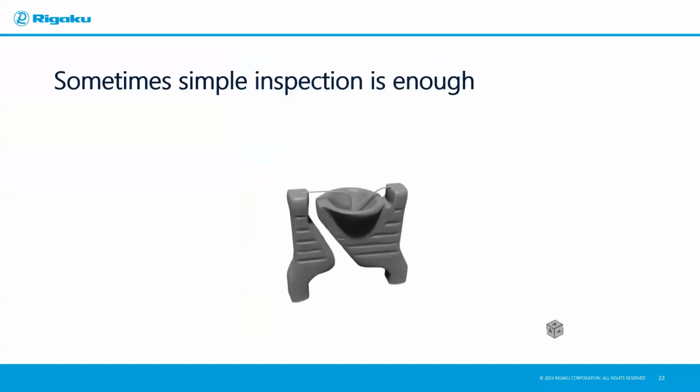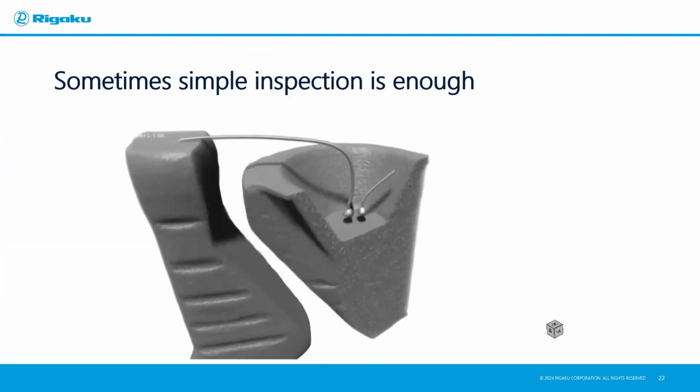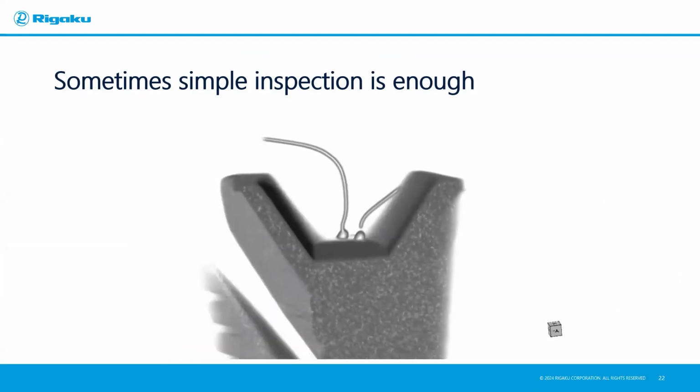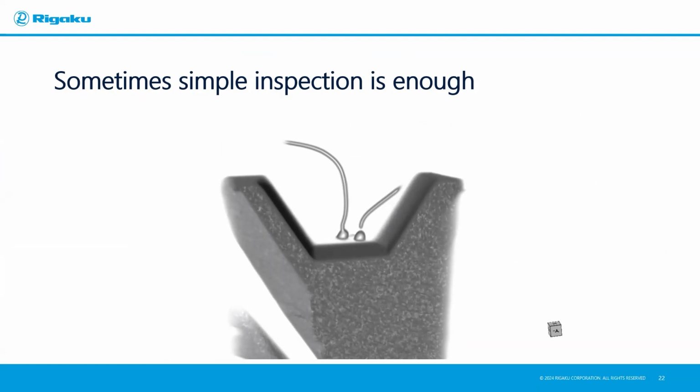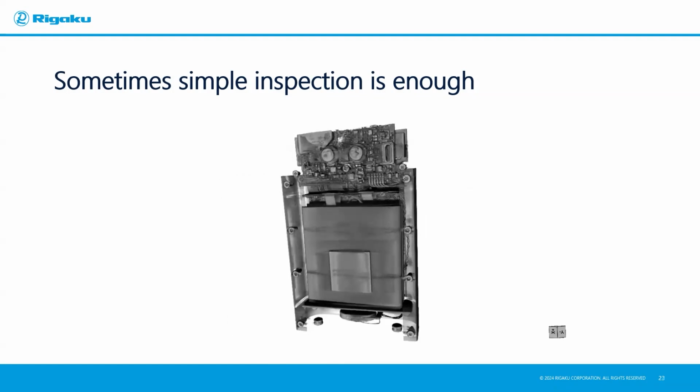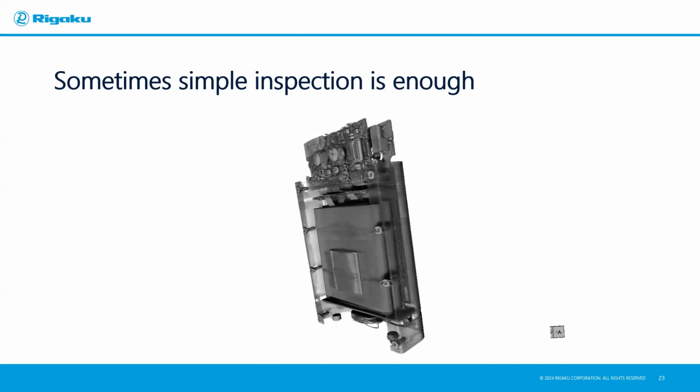This is a really simple example. This is an LED. There are plenty of those in your pool and in your controls, and they require a continuous circuit. So in this case, you can clearly see that there's a wire broken. And if you were imaging an LED and zoomed in on this area, you could clearly say, that's why it failed most likely. There may be problems elsewhere, but that's definitely a failure point.